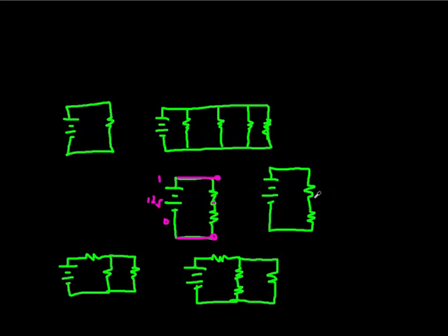Okay, let's move down here to the bottom where it gets a little more complicated. If you had 12 volts, that does not imply you would have 12 volts sitting right here. Why is that? Because some amount would get dropped across this resistor as we go forward. And whatever didn't get dropped by this, let's say 4 volts got used up and dropped across this resistor, that would leave 8 volts sitting right here. And there would be 8 volts here, and 8 volts here. Why? Because they are in parallel, and all this is one long wire. And if this was at 0 volts, this is at 0 volts, and this is at 0 volts here.